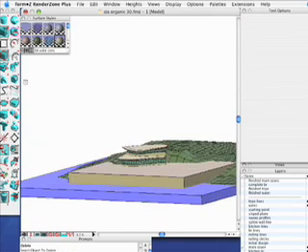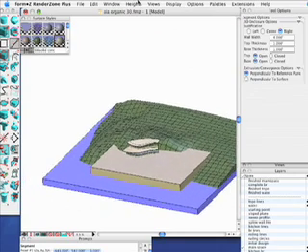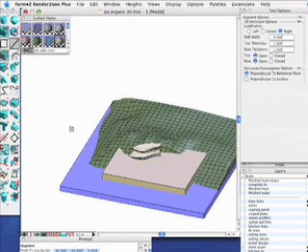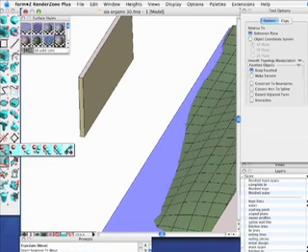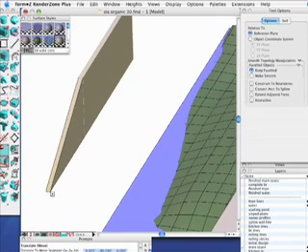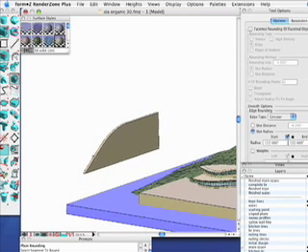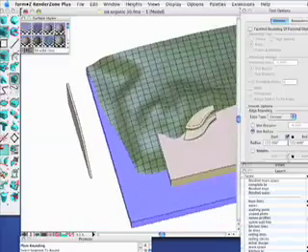I'm going to delete this because I want to show you another way you could create this same object. What I'll do is use a single segment, and I'm going to draw that segment out here. I'll extrude that upwards to about there. Next I'll take this bottom segment and move that outwards. I want this wall to taper down to a point, and I even want a smooth transition. So how about I round or radius that upper segment? So I'll set a radius of up over 100. I'll select that segment, so now you can see I have a little smooth transition there.